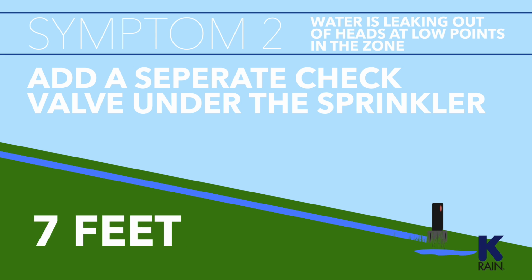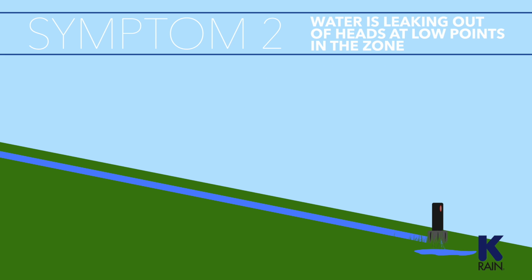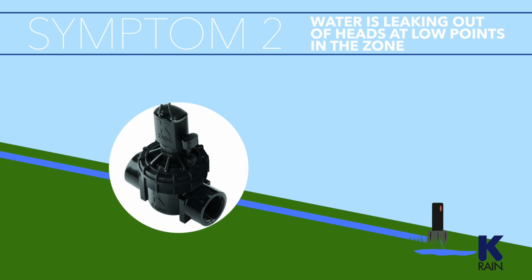If the wetting around the low sprinkler is continuous, the problem is more likely the valve. A weeping valve is one that is not fully closed and will generate a constant flow of a small amount of water that will find its way out through the lowest sprinkler in the zone. Open up and check for a damaged seat in the valve or a worn diaphragm. Repairing or replacing the valve will generally solve this problem.